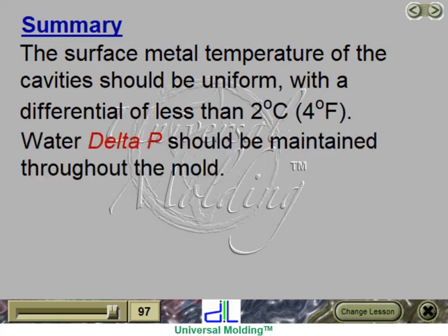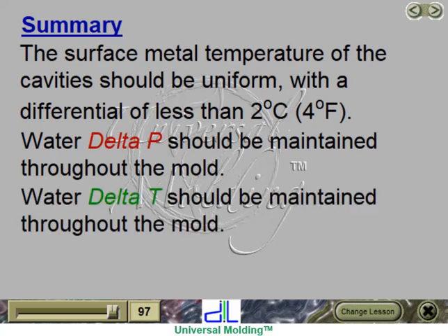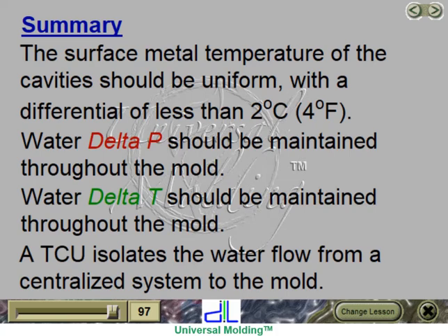Water delta P should be maintained throughout the mold. Water delta T should be maintained throughout the mold. A TCU isolates the water flow from a centralized system to the mold. Let's review.